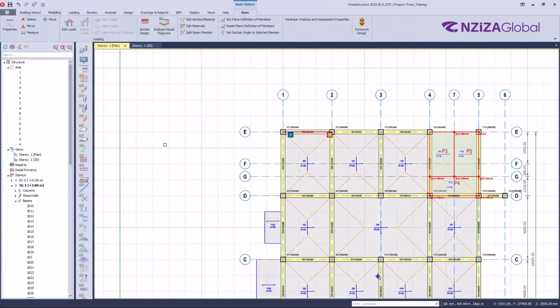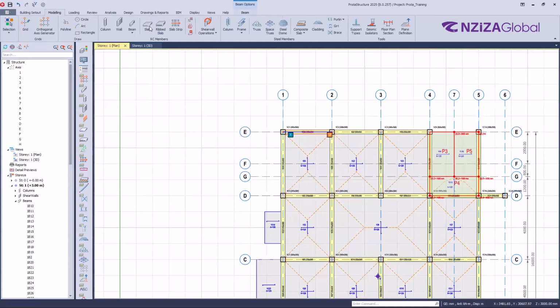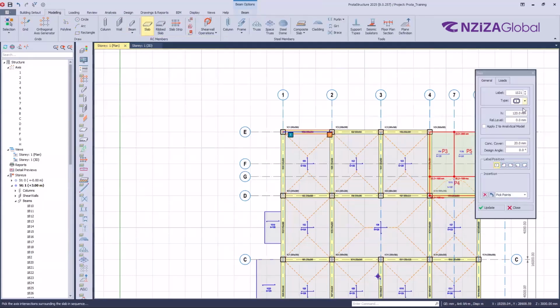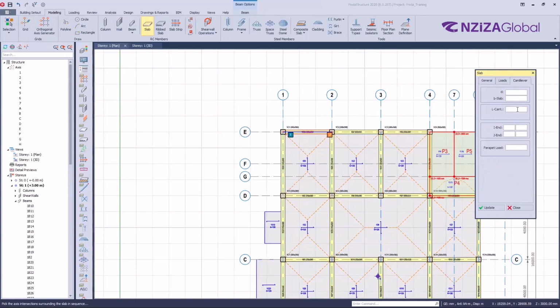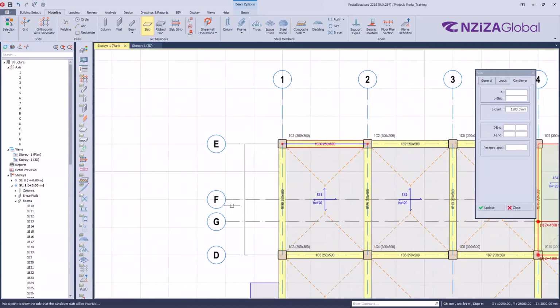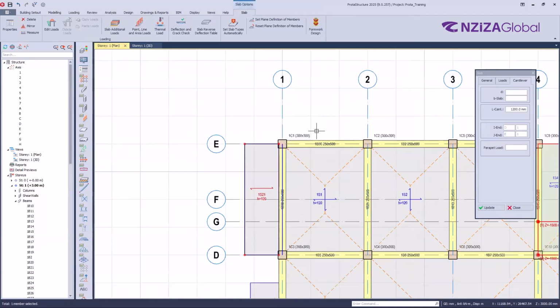In a way where you have the corner like this, if you are choosing to create cantilever slabs, for instance, from this point to this point, I will create a slab here. So if you create another slab here, the software will join those slabs automatically. So if I create another one here, you see automatically there is connection. So in a 3D view, it will be looking like this. Okay, cantilever slabs.